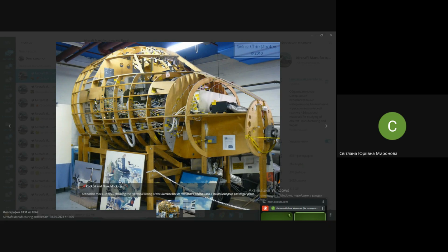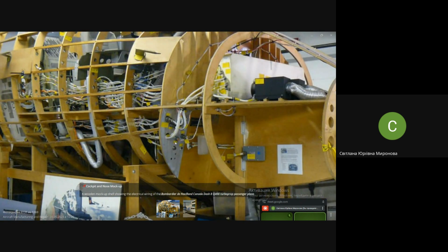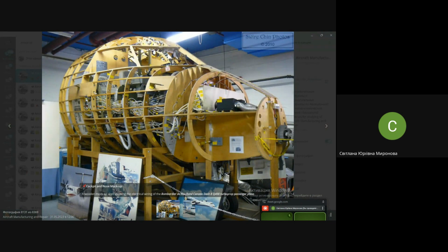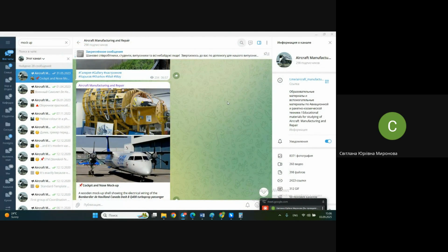You see, they check the coordinate positions of all the wires, of all the inner elements of pipes and other equipment, for instance, in order to make sure that all equipment corresponds to the sizes, to the compartments of the airplane, that all the places have access while assembling and so on. Before the appearance of 3D models and so-called virtual assembling, that was the only way to check all our decisions that we made on drawings before we started repeating our mistakes, do forgive me, in real manufacturing.